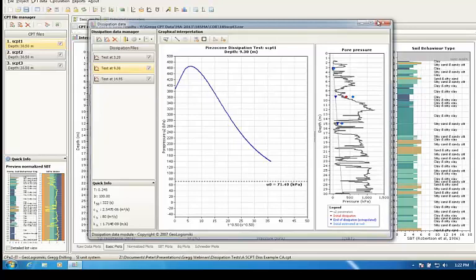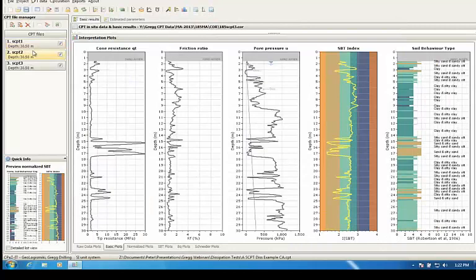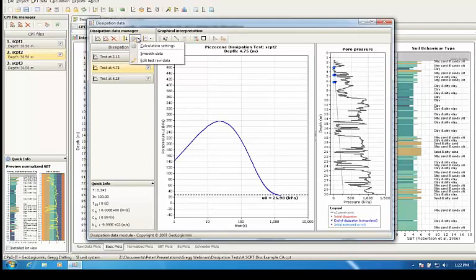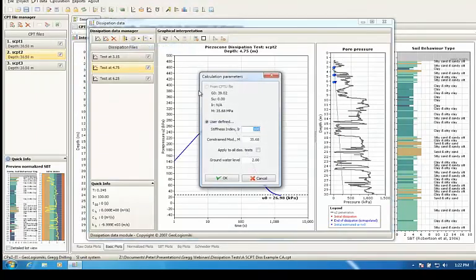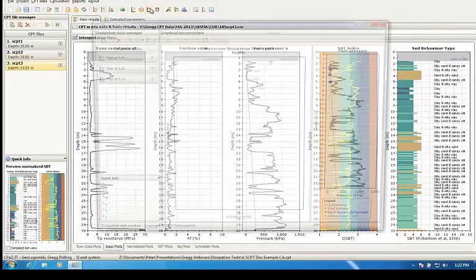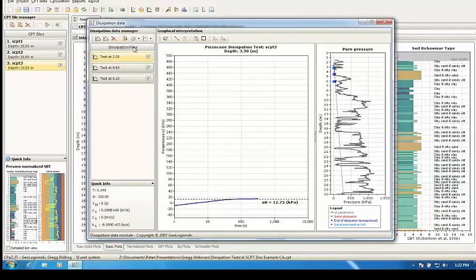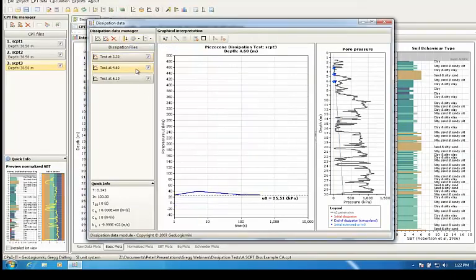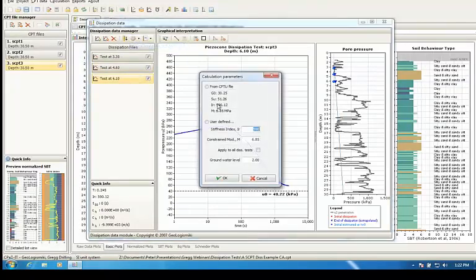Would you consider it reasonable to degrade G0 values to failure using the hyperbolic relationship? Yeah. You saw from the software that when you're interpreting data, you do have this option of going up into the calculation mode, and CPT says, at this particular depth, G0 in this case is like 47 megapascals, SU is 88 kilopascals. So it calculates the ratio of those two and puts it here.